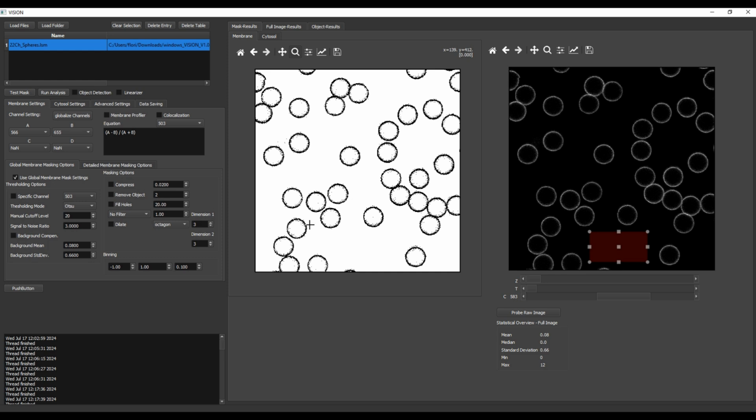The next point I want to show you is the filter. We have several filters here: the Gaussian, the mode, the median, mean, geometrical mean, majority, minimum, maximum, sum, gradient, entropy. Many filter types. I want to show you one basic filter, the Gaussian filter, where you can use this value to increase the Gaussian size, the filtering size, or the filtering intensity.